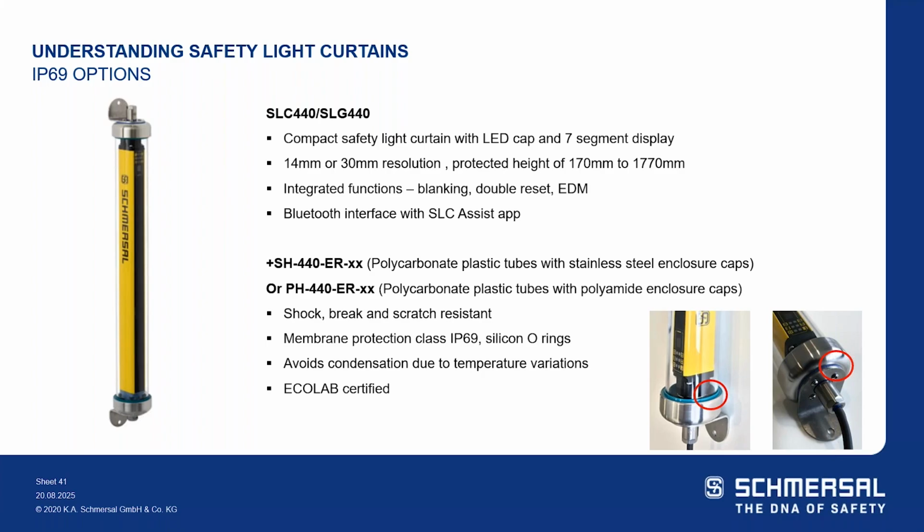Not just the curtains, but for the grids too. So on your SLC or SLG 440 series, your light curtain with the 7-segment display, you can have a polycarbonate plastic tube with stainless steel enclosure caps, which would be considered hygienic, or you have a PH, which is the polycarbonate plastic tubes with the polyamide enclosure caps. So they're shock and break and scratch resistant, membrane protection class IP69 with silicone O-rings.